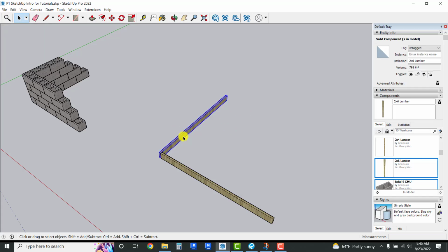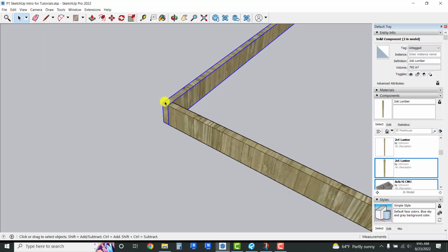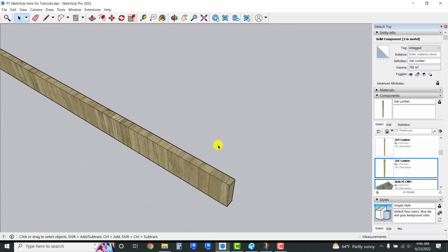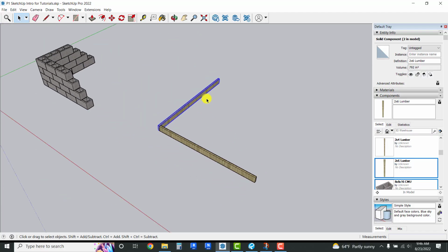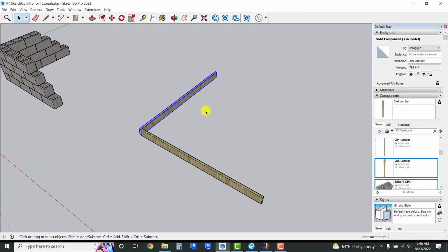Now I will select that first rim. And when I copy, before I select the command, I'll show you, we're going to copy from this outside corner. That's going to be our move from, and we're going to attach that corner to this corner so that it's a single motion copy, and we won't have to move it once we get it on the other side.